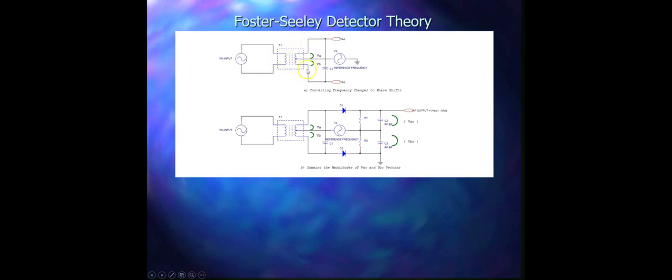frequency of this tank, at that time the phase shift is adjusted to be 90 degrees by tuning T1. So at the top output here, you will get the phasor sum of voltage VC and VA. A voltage VA will be developed over here and VB voltage will be developed over here. So at the top you will get VAC voltage, and at the bottom you will get VBC voltage.